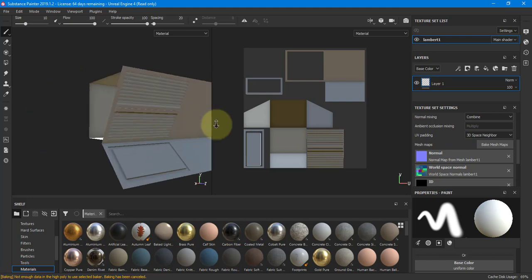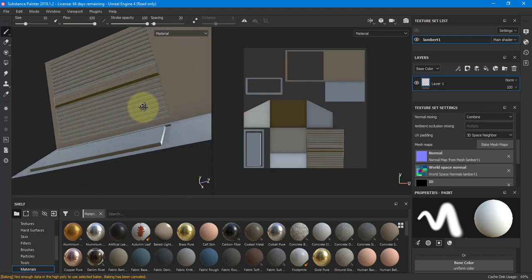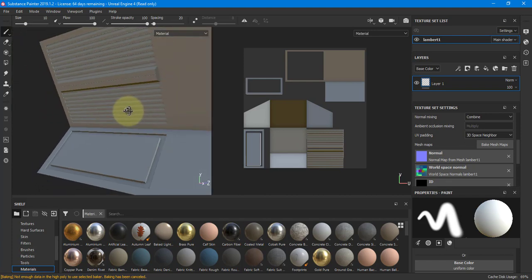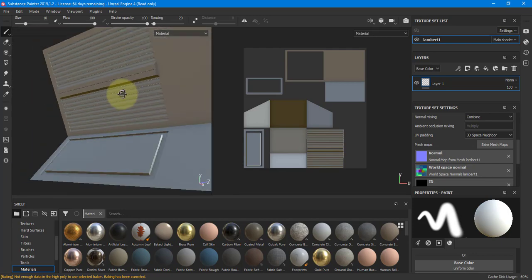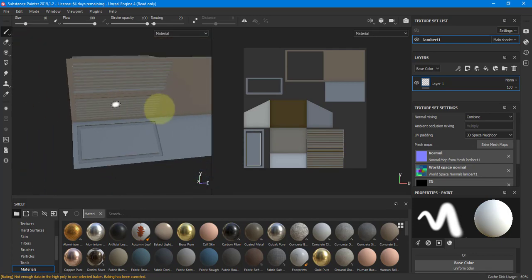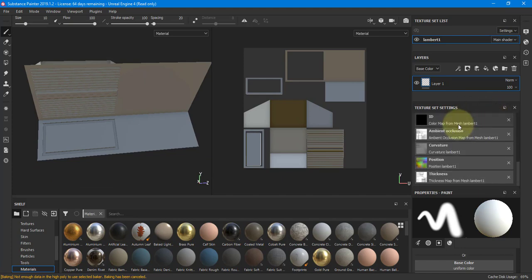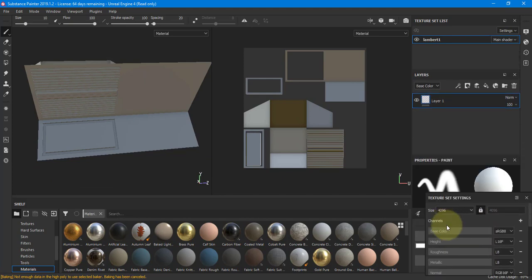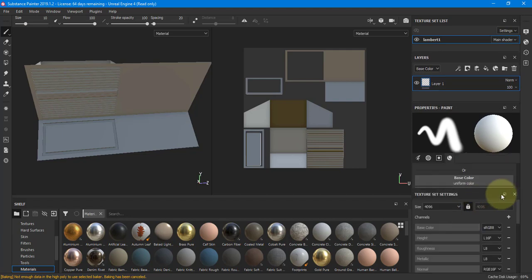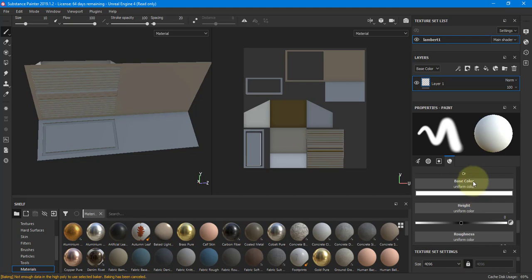So there are our maps, okay? This generates, and you can see it already has some kind of shading to it. We're seeing some ambient occlusion locked into this. It's not really anything else; the ambient occlusion is the main one. Okay, so we're pretty much done with this texture settings tab for now. I don't need to see that anymore. I'm just going to throw it down the bottom here and make that bigger. There we go.